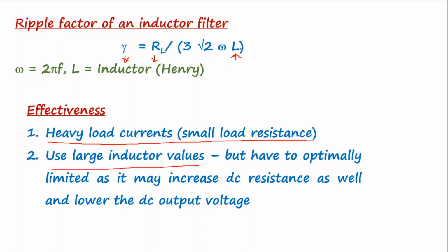But then you have to think about one more thing. Apart from the reactance, that is its resistance to the AC component, the inductance coil also has an actual resistive part, the resistance it offers to the DC component, and that is the normal R. So apart from the XL value, the reactance, it has its inherent R property as well.